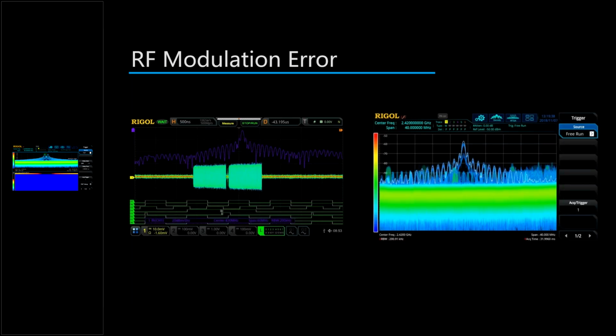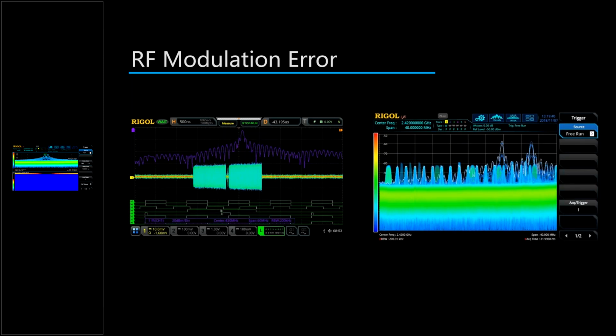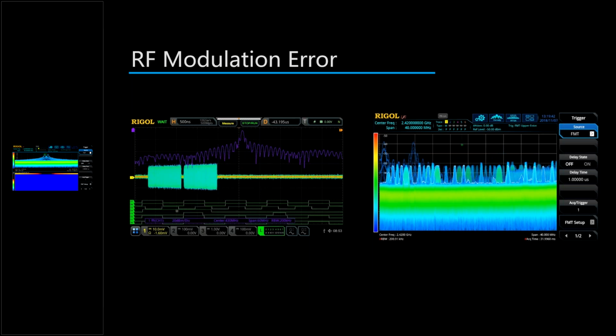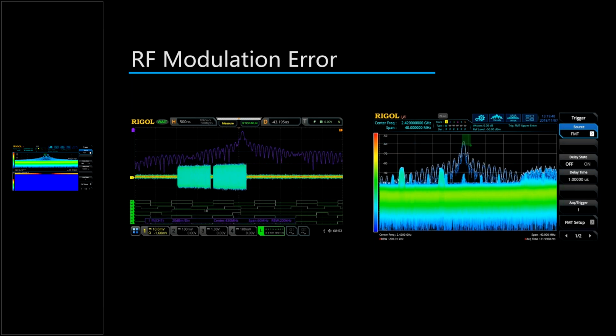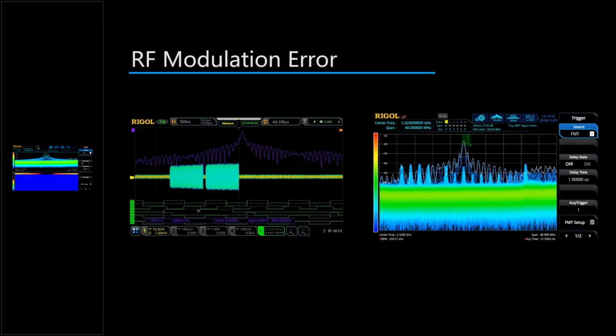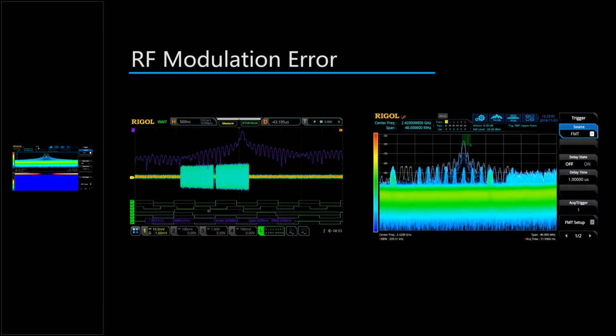And here's an easy way to look at that video in sequence. Probably best to do this side by side. So we can see as we switch over and capture the individual frequency mask on the analyzer on the right, we can then see its triggers on the scope always in the same frequency bucket. So now we can look at those broken pulses as they're triggering in individual frequency buckets. So being able to slice these problems either by frequency, by power, look at those pulse shapes, and then ultimately problem solve regardless of the cause. It's a great way to capture and look at these signals.